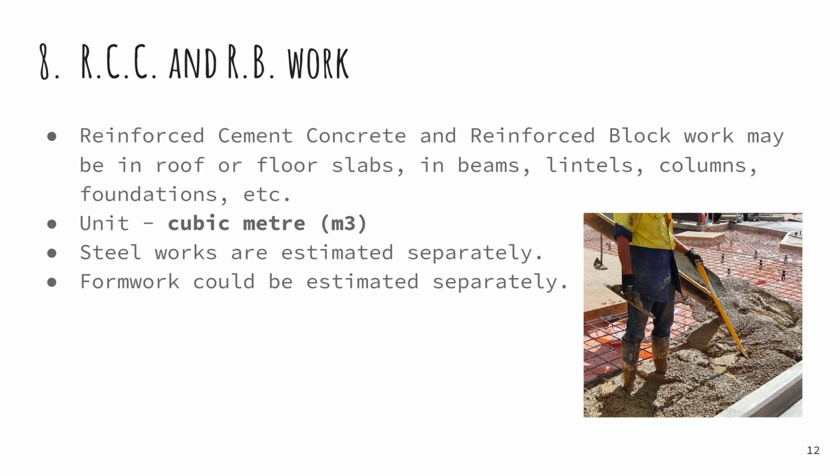And you can also see reinforcement bars here. Actually, reinforcement bar is never calculated together with the RCC work. So RCC will be estimated, but the steel which is a part of the RCC is estimated separately. So you just have to be careful about that.